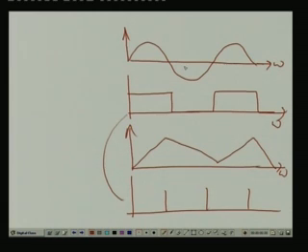But as you know, in crystal oscillators also we are basically generating a sinusoidal wave. Then we are passing it through a Schmitt trigger, and we are making a square wave. So, there are many oscillators, such as the Wien-Bridge oscillator. Why should we go for crystal oscillators as a piezoelectric based oscillator? Because of the frequency stability. In a Wien-Bridge oscillator or a phase shift oscillator, you won't get that type of good stability, right.